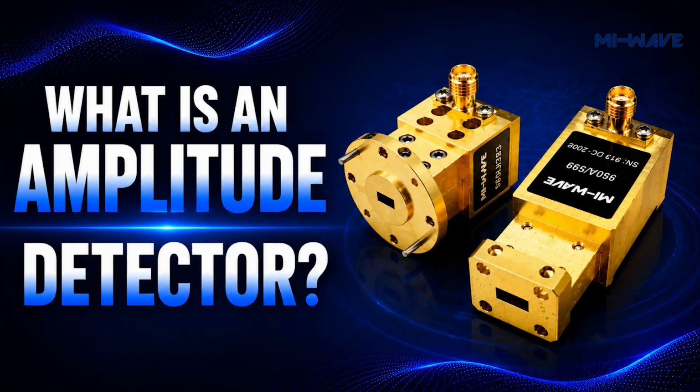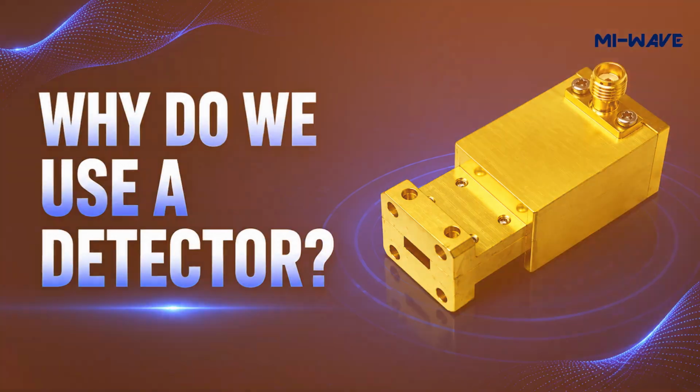Let's start with the basics. What is an amplitude detector? An amplitude detector converts RF power into DC voltage. Instead of measuring a high-frequency RF signal directly, the detector produces a low-frequency voltage that can be easily measured using standard instruments. This makes RF power measurement much simpler and more practical.